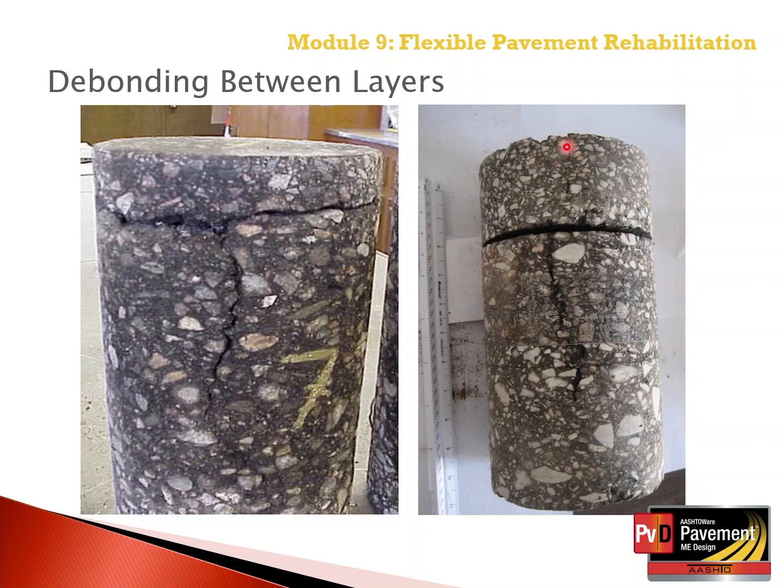So deflection testing and back calculation, as well as the use of cores, could indicate some structural deficiency regarding debonding between the layers and result in a different rehab option, including a deeper mill and replace with a thicker overlay.